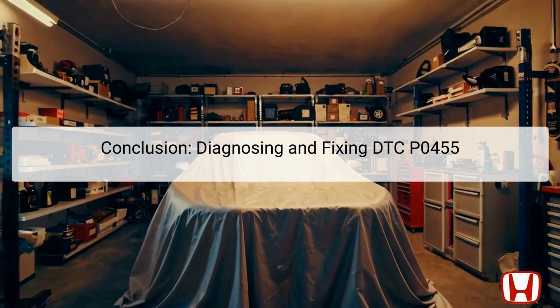Using proper diagnostic tools like the Honda HDS, vacuum gauges, and pressure testers is essential for accurate troubleshooting. After repairs, system reset and verification are critical to confirm the issue is resolved permanently. Maintaining the EVAP system through regular inspections greatly reduces the risk of future leaks, ensuring the vehicle remains environmentally friendly and compliant with emission standards.